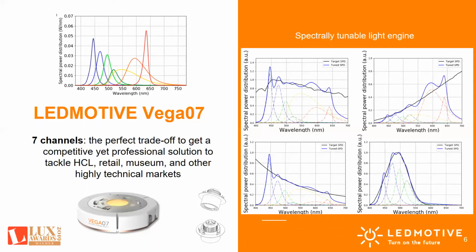And this is not a tunable white solution nor an RGB light bulb. This is a full spectral light source with the best flexibility to create visible light spectra and control the light levels. These four examples show how we can tune the different channels in order to match any target spectrum: daylight D65, an incandescent spectrum, a black body of 7000 K, and the melanopic spectral sensitivity function.